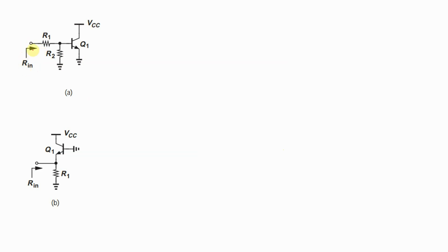The classic way is to place the small signal model of this bipolar junction transistor, place VA test and IA test, and calculate the fraction of VAT divided by IAT. But I'm just looking at the circuit and calculating the Rin without using KVL and KCL, just seeing the resistance from different nodes. So just start at the end. Here for this Q1, what is the resistance seen through the base of this BJT? It's actually R pi with a subscript of 1.